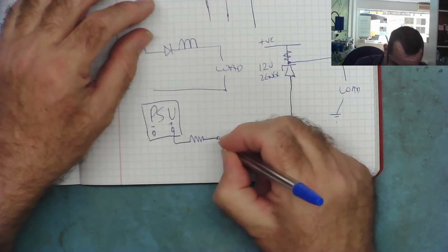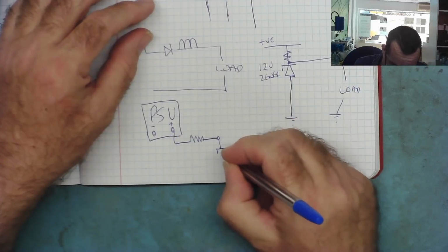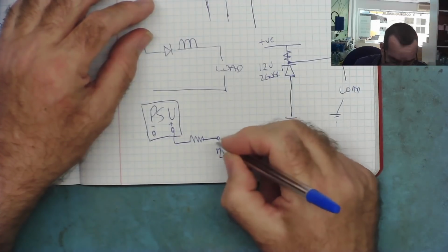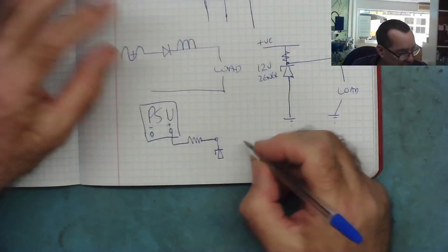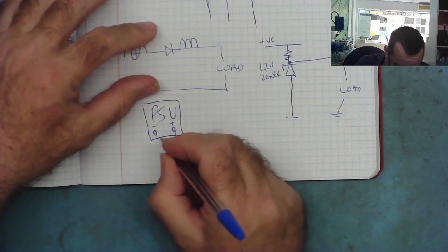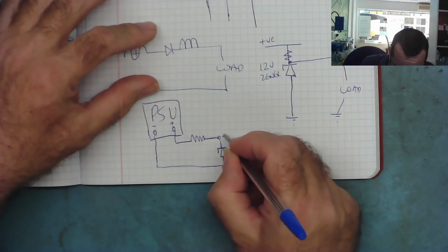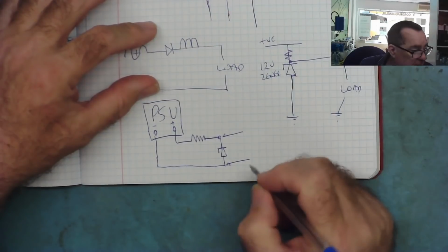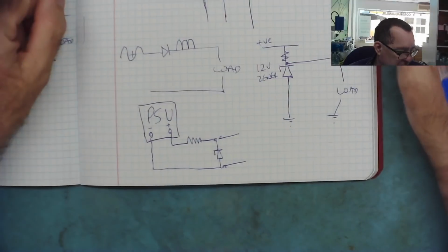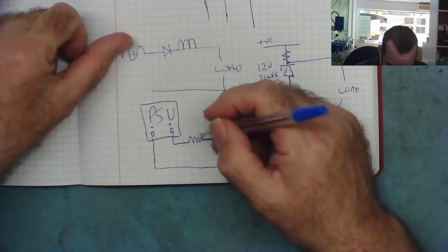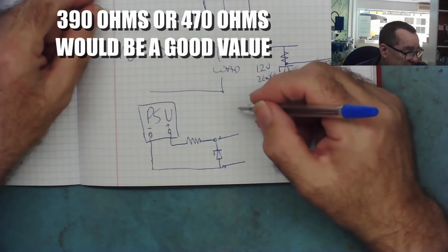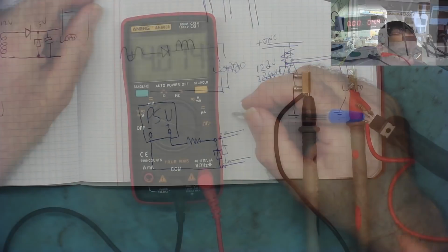So this is where we want to test the diode. We connect it this way round with the cathode towards the positive, back to front for a normal diode, and we connect it like so. And we can take our voltmeter and we can measure from here to here, and whatever voltage we measure is the Zener voltage. The resistor isn't particularly critical.